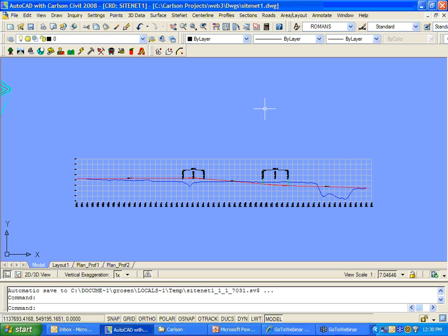Sorry. Go ahead. What else you got? Well, let's see. Some other questions revolved around the name of your title block, the drawing that you had. Can that be located on a server location? And does it have to be called profile, for example? So those can be put on a server location. You just have to have your AutoCAD path to go and find those drawings, whatever they're called, in whatever location. You just need to append that to your AutoCAD search path.